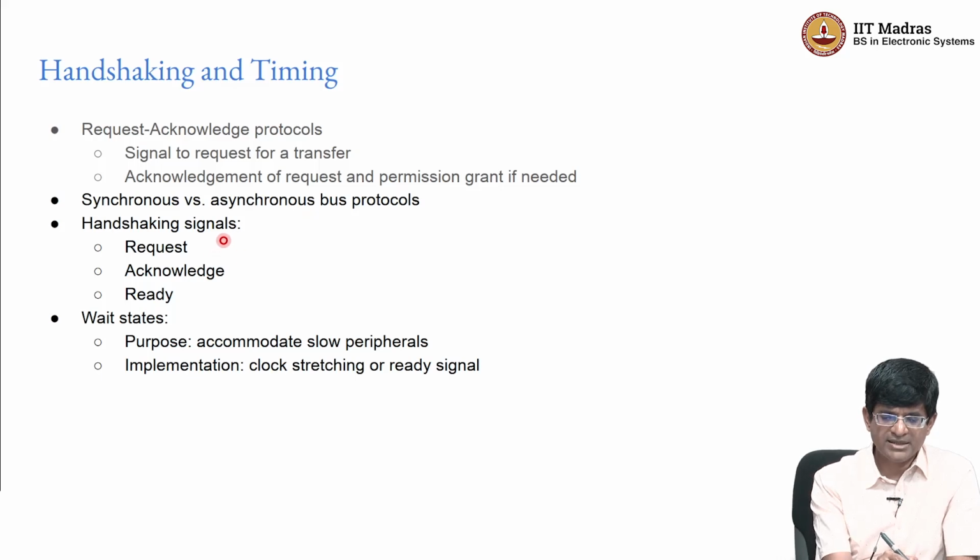Handshaking essentially is useful in such scenarios, right? What we do is that the CPU requests data, the device that is trying to give back the data acknowledges the request but may not give back the data, and finally it gives back the data when it is ready, and the CPU can then accept the data and do something with it, right?